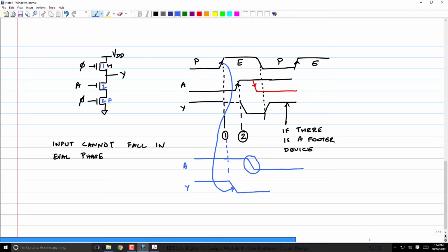Logical effort is some estimate of how long it will take for the output to go high or low. But for the output to be high in a dynamic circuit, you only have to look at what happens in the evaluate phase. By the time you are at the evaluate phase, the pre-charge has already taken it high. So there is no delay in taking the output to a logic high, and therefore pull-up logical effort is irrelevant in this case. It's not zero. It's irrelevant.